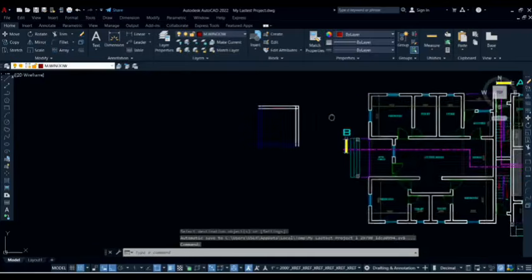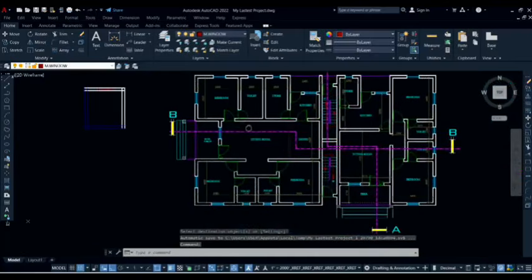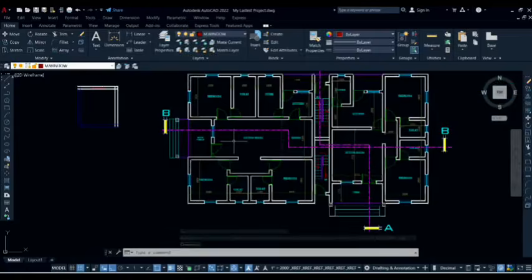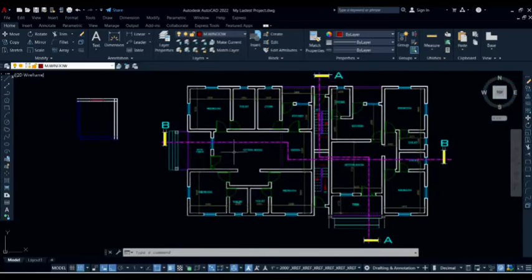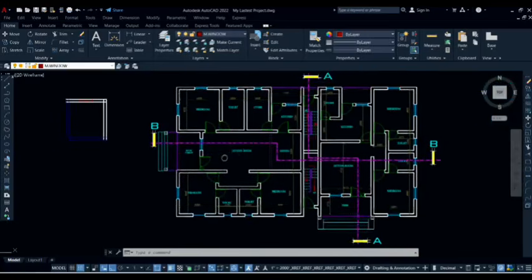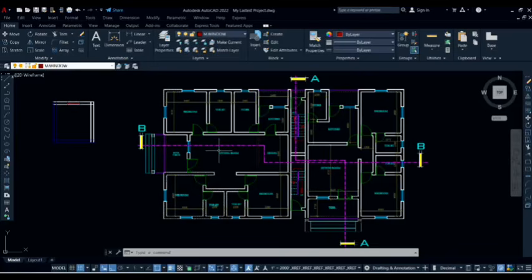That is for that. Also, we have the layer isolation. Now we are going to use this drawing to practicalize the layer isolation. So now let's click on the text. You see this is the M text. So we go to the layer tool because we want to isolate the text.